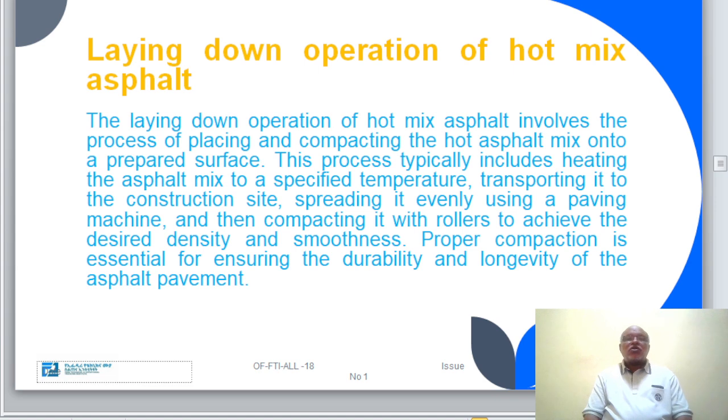Some manufacturers offer pavers that are also equipped with a spray in front of the screed for spraying the tack coat. These pavers spray the tack coat and apply the hot mix asphalt seconds later. They are also known as spray pavers or integral pavers.